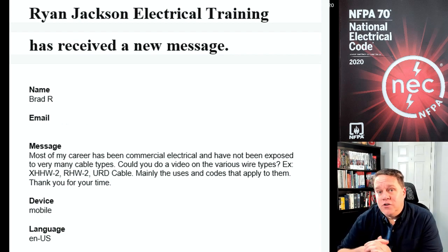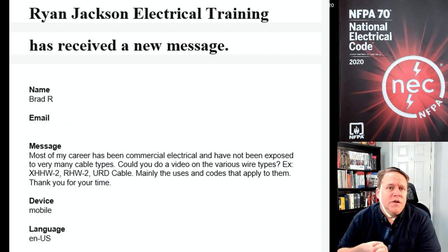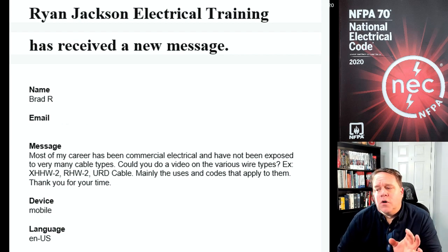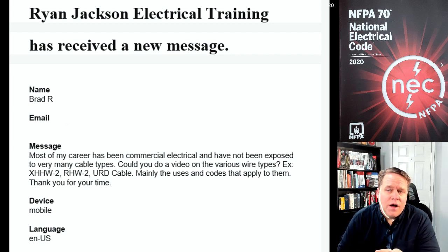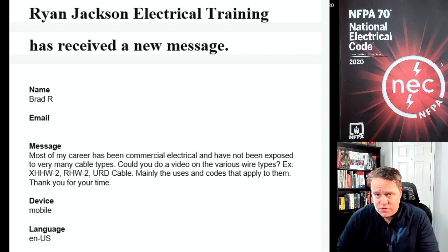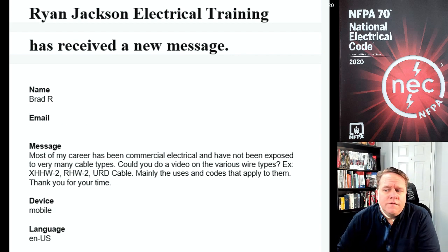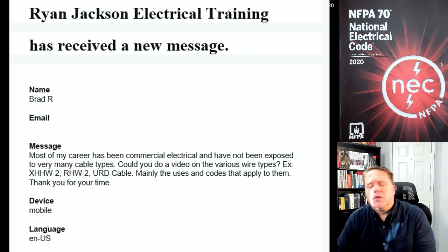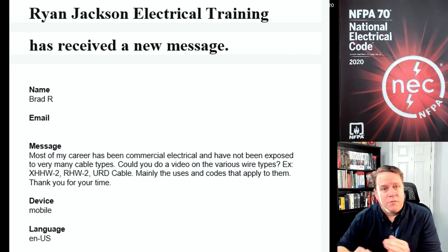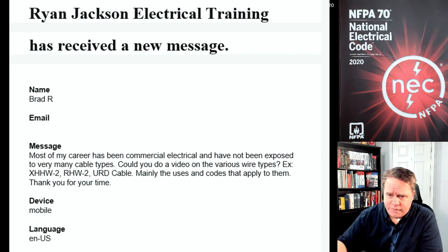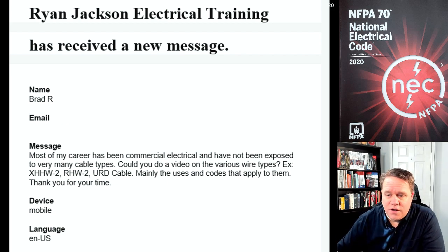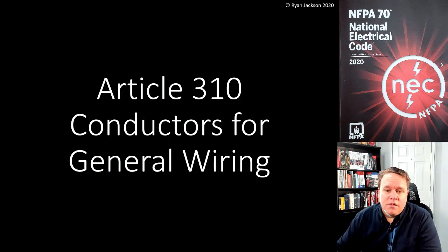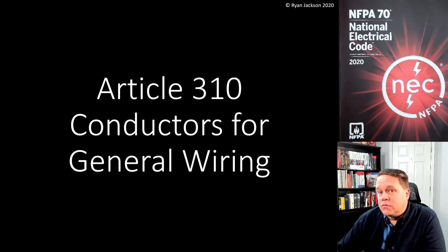We're going to talk about USE conductors, but in case I forget, they're also newly added in Article 338 in the 2020 code. Take a look at 338.2 for the definition of multi-conductor assembly, and 338.100 for some construction specifications. So before I forget about URD, which again I'm going to forget because there is no URD. It's not a thing.